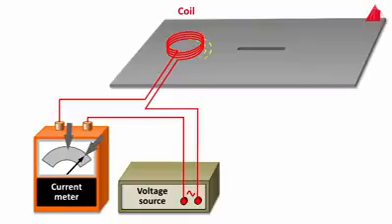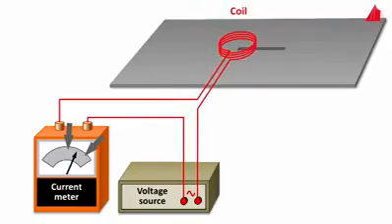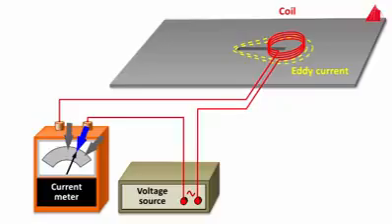Once more, the reason is an eddy current that flows in the sheet in close vicinity of the coil. The eddy current again creates its own alternating magnetic field which counteracts the magnetic field of the coil and reduces the inductance. When the coil is located over the saw cut, the current consumption drops. The eddy current can no longer flow freely and must take a detour around the saw cut. This in turn decreases the strength of the eddy current. The magnetic field of the eddy current is weaker and interacts less with the coil.